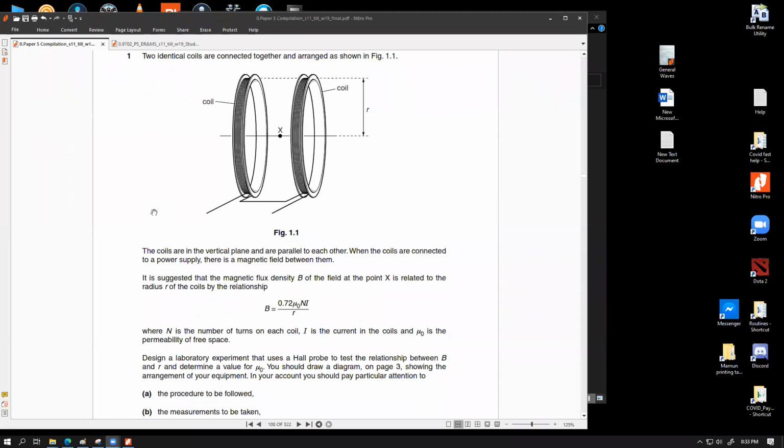That's the workable circuit. The purpose of the ammeter is to measure the current so that you can observe the value of the current. The purpose of the variable resistor is to increase or decrease the resistance of the circuit, so that the current can be maintained at a fixed value throughout all of our apparatus setups. This is very important, because we have to keep the current constant. So to make sure that the current is constant, we need to have a way to view how much the current is, that's where the ammeter comes in. Then we need to have a way to control the value of current, that's where the variable resistor comes in. So all of these things should be connected in series in a workable circuit.